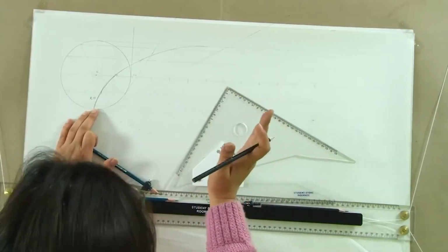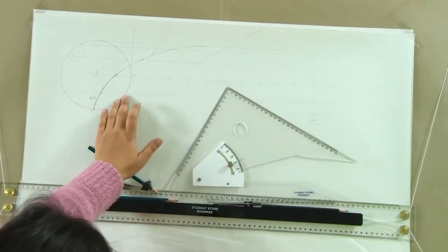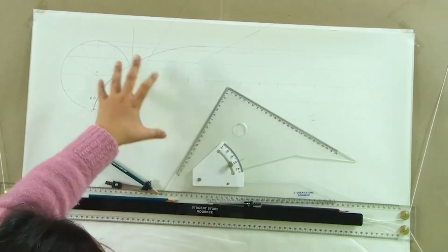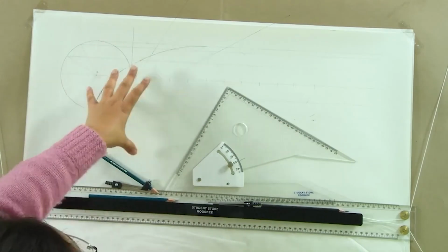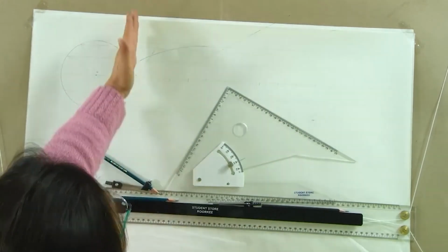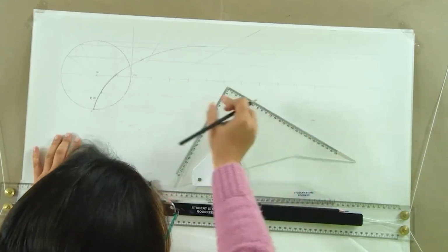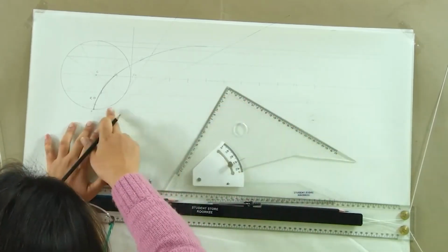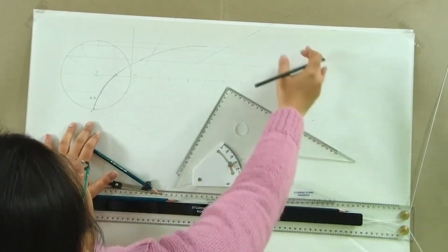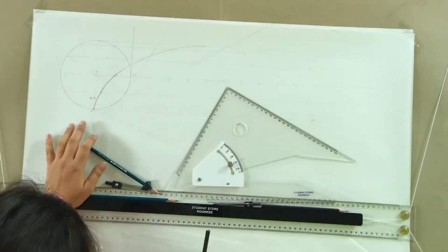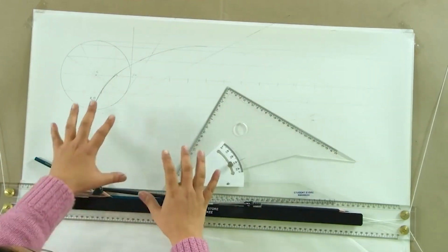In a circle it is easier to know what the tangent is, but in a square we would just be extending the side of the square on which we would cut the length equal to the leftover perimeter, and that is how we would get the involute. So, I hope it is clear how to draw the involute of the circle and square, and following the same process you can draw the involute of any 2D object.